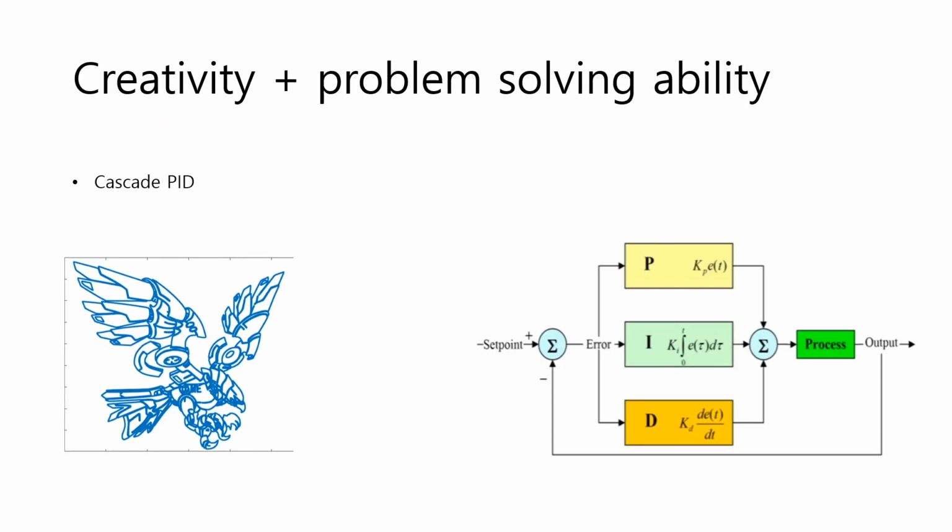For our system, we have a so-called cascade PID controller. Since we want our system to react and respond to disturbances, we use a closed-loop PID to give an appropriate voltage to the motor. However, we have added another PID loop to separate disturbances from various sources. The second closed loop uses the velocity of the motor to change the input voltage, which affects the feedback of the outer loop. We have two closed-loop PID controllers in the same system. By literally taking a closer look at our diagram, we were able to think of a more advanced method of control with the same principles. This control method allows us to reach our desired positions much faster than the single PID control method without the risk of oscillations or divergence.